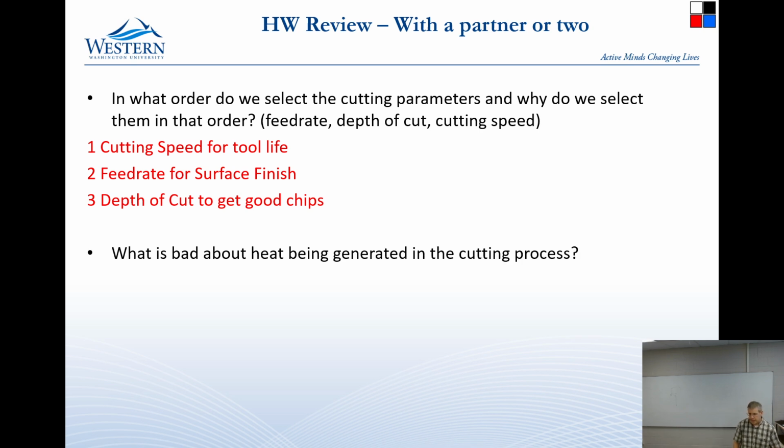What is bad about heat being generated in the cutting process? Okay, you can weld the material to the tool, and then the tool is failed, even though the tool underneath is just fine. But you, in general, cannot break it off or unweld it easily. All right, what else?